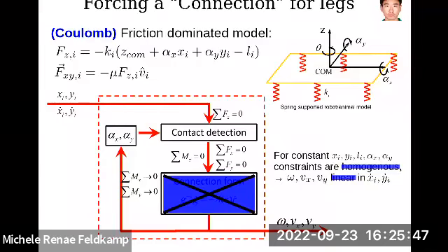So if all the friction coefficients increase by the same multiplier, the result remains unchanged. That means that, at least to some extent, the system is invariant to the surface. The only thing that changes is the magnitude of friction. As you switch from surface to surface, you'll get the same answer. You only get weird things when some of the legs are on one surface and some are on another.